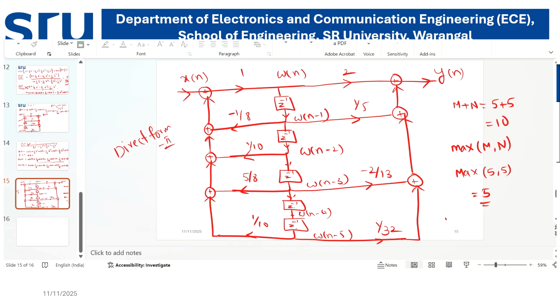Therefore, the number of memory locations required in direct form 2 has decreased from 10 to 5. That is the advantage of this direct form 2 structure. The memory requirement is less. If memory requirement is less, it is less in construction. If delay elements are less, then complexity will be reduced. The circuit will give fast output. These are the advantages of the direct form 2 structure.